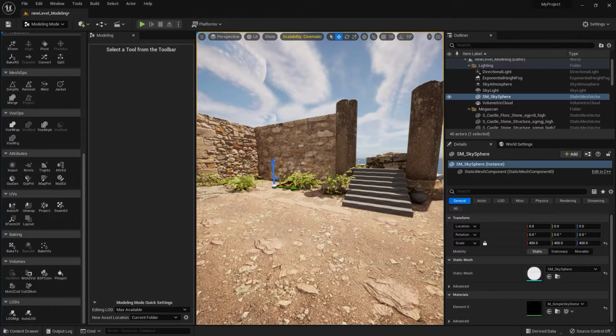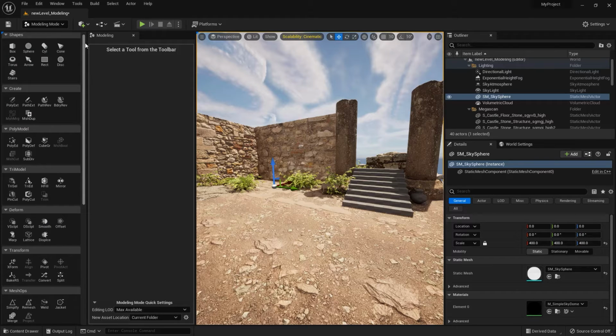Now, polygroups are collections of triangles, which can be defined by a variety of tools in this modeling editor. So as long as you have polygroups, you can actually select a bunch of quads and n-gons with nothing to worry about. Let's have a look and see the modes of the pre-existing polygroups as well as how to create our own custom polygroup.